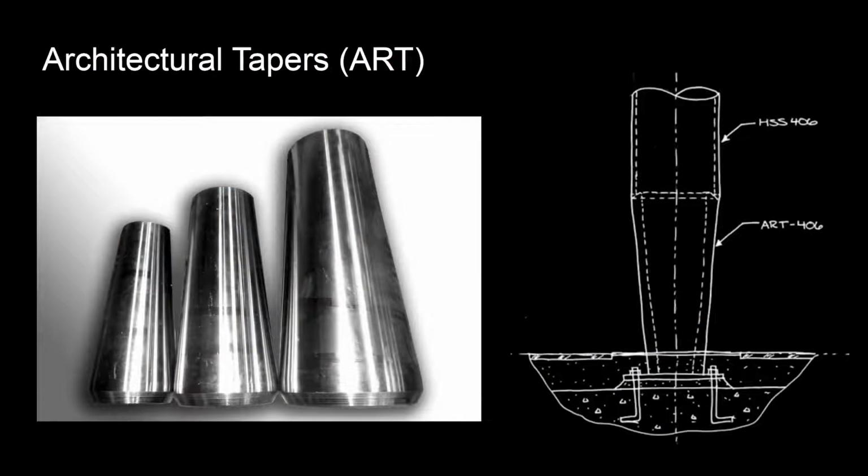As I said, there's lots of different shapes and standardized castings that are available. There's tapered ends that you can use, say, for example, to pencil the top and bottoms of exposed columns. And you'd be surprised just by penciling just the tops and bottoms how it makes that whole column look more slender. Your structural engineer is saying, I need a certain size so that the column doesn't buckle. But at the ends, you can pencil it down and make that whole column look so much more slender. And there's standardized fittings that can allow you to do that.